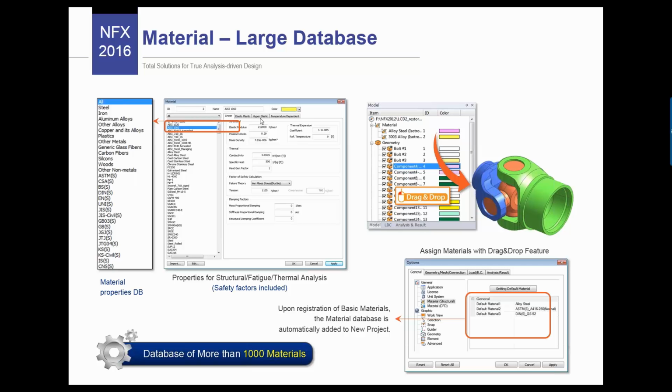And if you want to do nonlinear analysis and use nonlinear materials, you can also consider elastoplastic and hyperelastic or other types of material which are fully supported. For example, what you can do is implement the full stress strain curve inside the software to use that. But this is a bit more advanced.